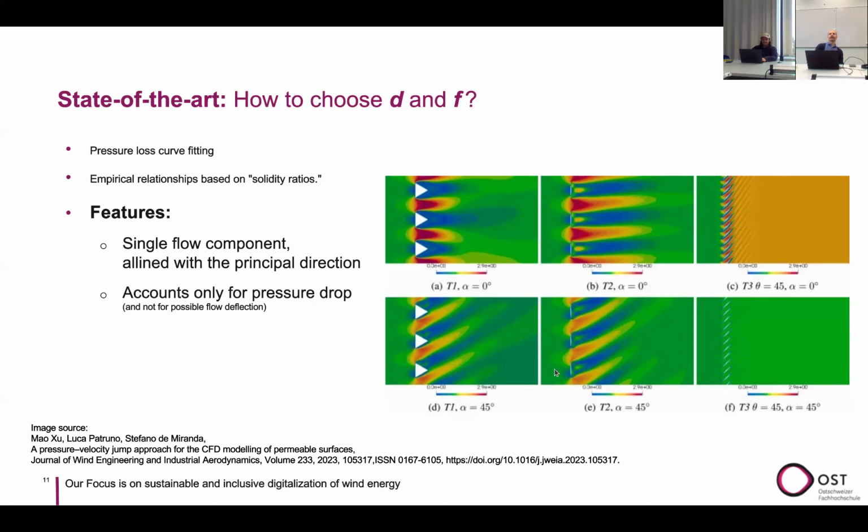But even if it's not a louver, just a perforated screen, the flow that comes into the screen at a certain angle is going to come out at a different angle, because there is some resistance being introduced in a tangential direction. So, for example, if the flow comes in at 45 degrees, the outflow is going to be deflected, let's say to 40 degrees, for example. It is obviously going to depend on the screen and the configuration.